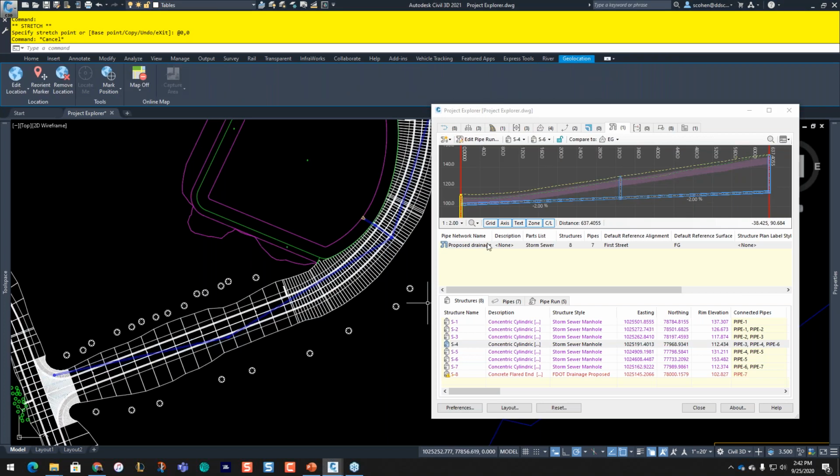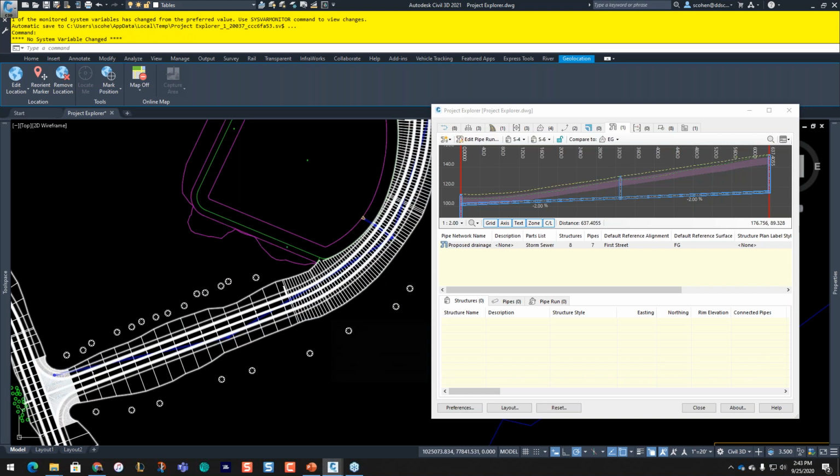Again, the thing I'll mention is, if you have non-connected parts, like let's say you're doing a roadway job, just a rural project where you have some cross drains, maybe some DBIs going to a pond, it doesn't work. I'll just tell you that right now. You'll get a little error message in this view that says it can't do it. I contacted Autodesk support and said, hey, I understand why it's not working, but I would like to have the functionality, because I had 3 or 4 where I had them connected, and it still wasn't doing it because it wants to do the whole thing. So basically, they're going to look at that, and it may or may not work. It's not a huge deal because I don't have that big of a drainage network as I have here.